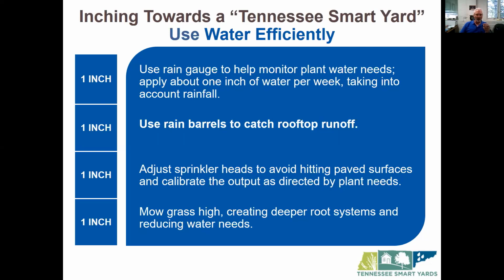By collecting that water, we reduce the amount of runoff that leaves the property. Those uses may be to irrigate our landscape, to wash windows, cars, okay? One advantage, especially in Middle and East Tennessee, is that rainwater will not have the hardness. It will not have the calcium dissolved in it that our municipal water does. Therefore, as the surfaces that we wash dry, water spots will not be left behind, especially on the car after you wash it.